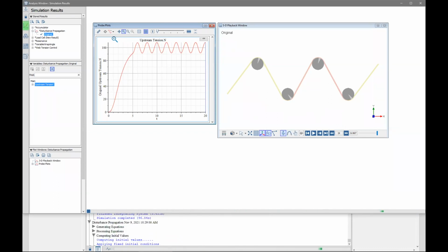We have the formulation for the friction, and that will increase the friction force and tries to minimize the speed error between the web and the roller. And that would result in better isolation for the upstream section. Obviously, if we selected no slip, there would be complete isolation of any disturbance downstream.